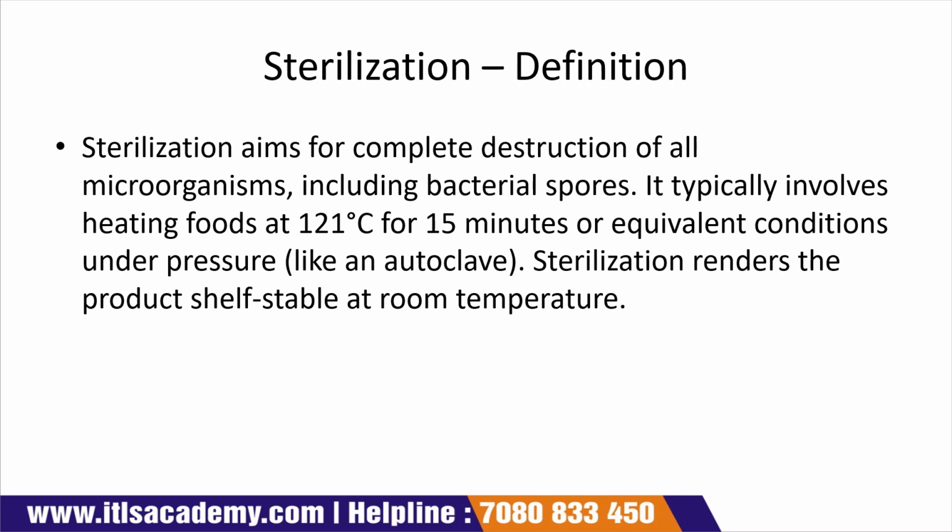Here we typically use 121 degrees Celsius for 15 minutes under pressure, same as with an autoclave. The sterilized product can be stored at room temperature with shelf stability, but once you open the product, you have to keep it in refrigerated condition.